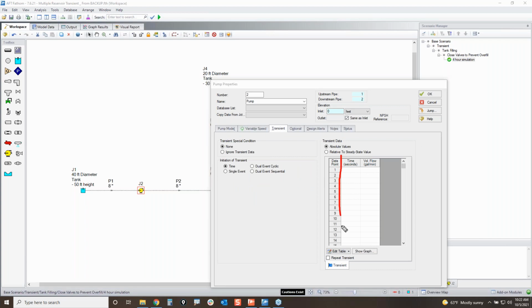You can define that as flow demand versus time data, and then you can see how your system will respond to that. You can do that for your pump or control valves or regular valves where maybe you know how their position changes over time, or a simple assigned flow junction where you have a flow demand somewhere and you're using that as a boundary junction.